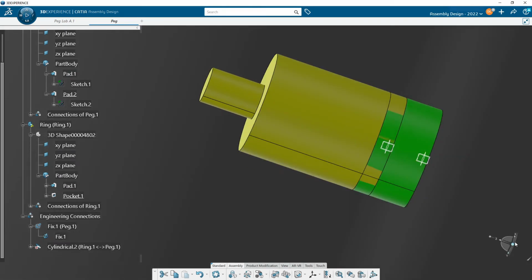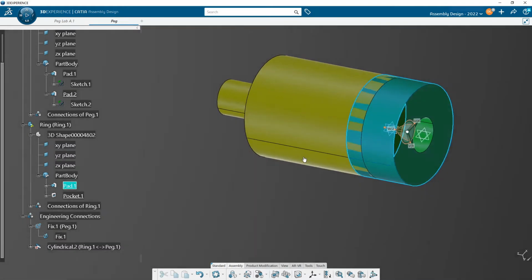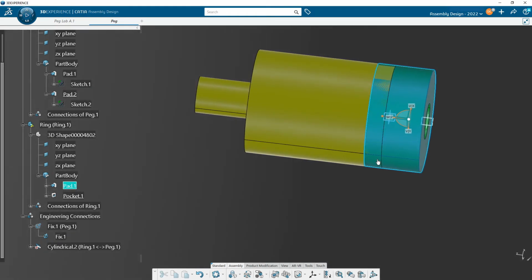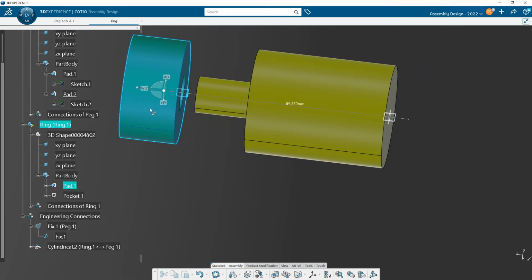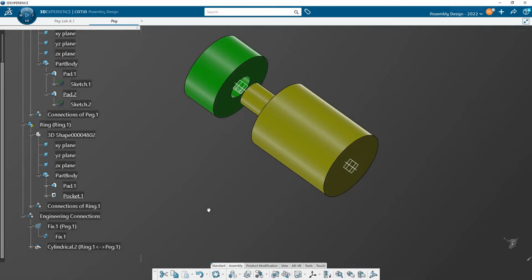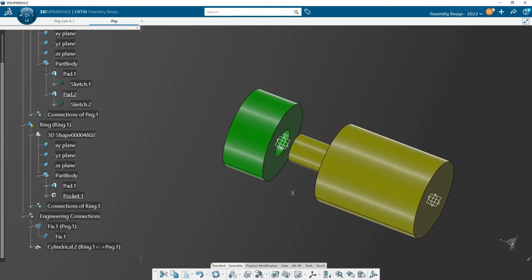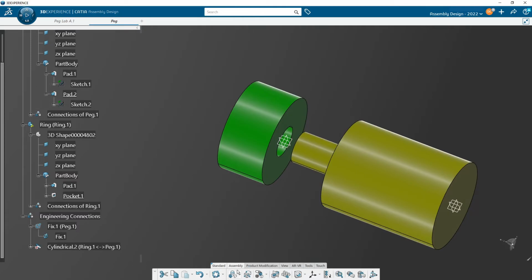So just know that I can come out here still, and I could stick my compass to that part. By the way, did you notice that it kind of grabs the axial center because I dropped it on the side? And then I can move this all the way up here somewhere. I cannot move it side to side because it is constrained center to center. Okay, coincidence. Drop this. Okay, and then next we're going to make a new one.